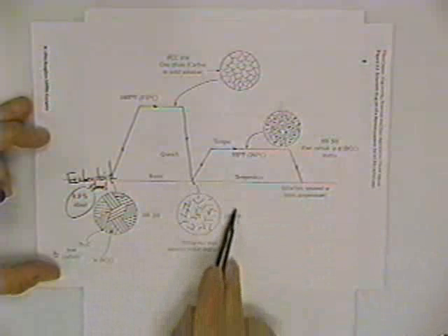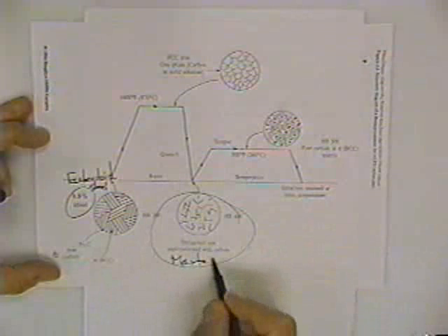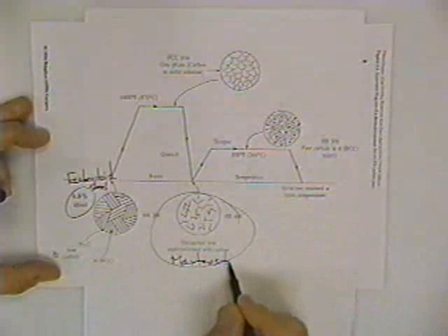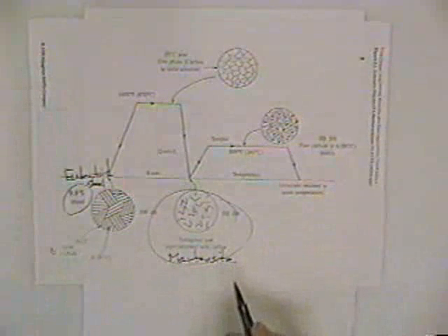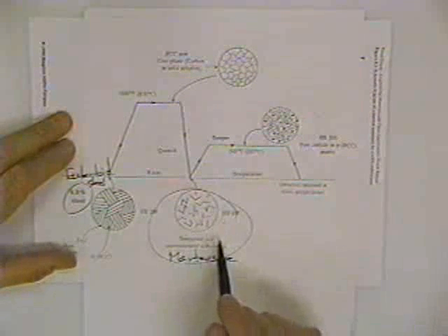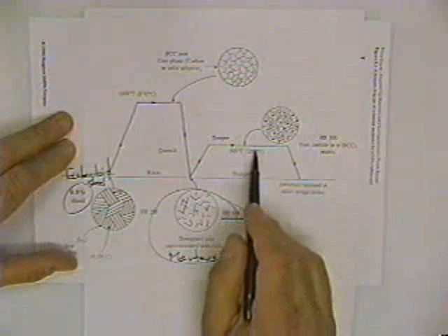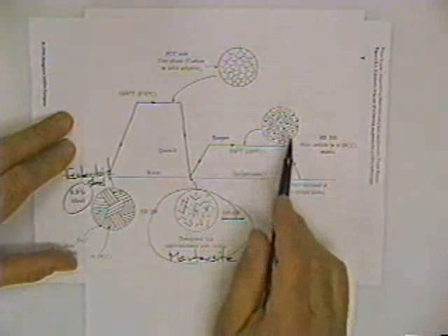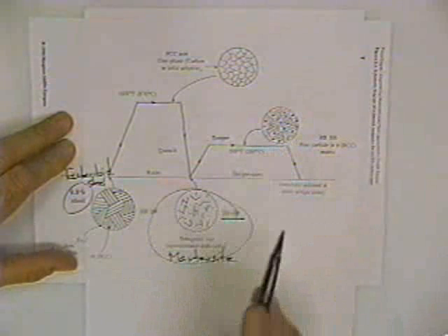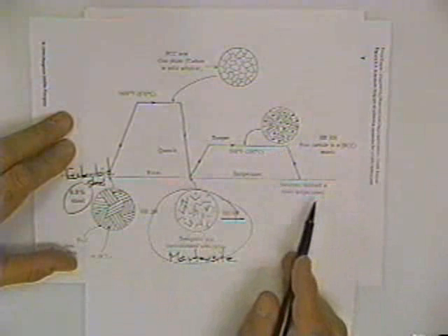In this condition, in what's called martensite, this is an incredibly brittle material, has almost no uses except for some wear applications. It doesn't have much fracture toughness, and very little ductility, very hard. So the tempering operation redistributes the phases so that we have an increased strength, decrease the strength and increase the ductility, but more important, we increase the toughness of the material.